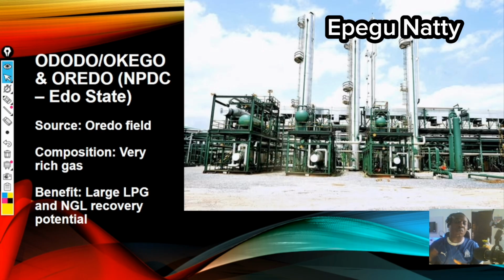EPF fields, early production facilities, and then they are all tied in and then sent to this gas plant for processing. All right. So the gases coming out from their three-phase separators, from, let's say, separator 1, separator 2, or separator 3, both the LP, the MP, and then the HP gases are tied in and then sent to this gas plant for processing. Now the gas here is very rich gas. They have a very rich gas.